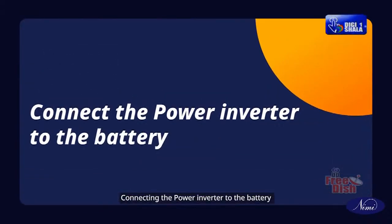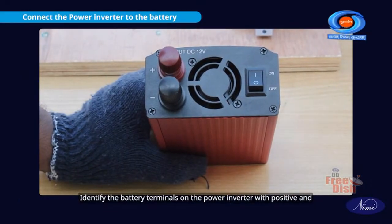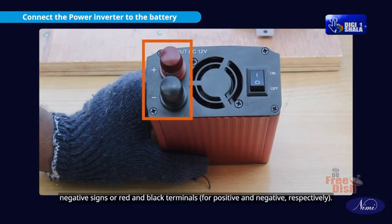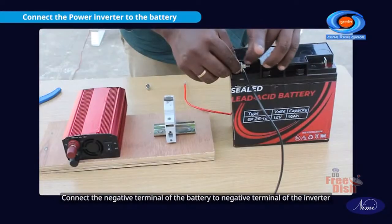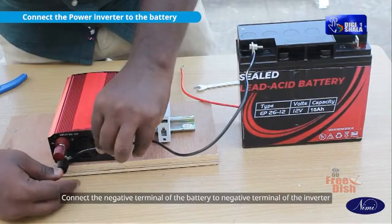Connecting the power inverter to the battery. Identify the battery terminals on the power inverter with positive and negative signs, or red and black terminals for positive and negative respectively. Connect the negative terminal of the battery to the negative terminal of the inverter.